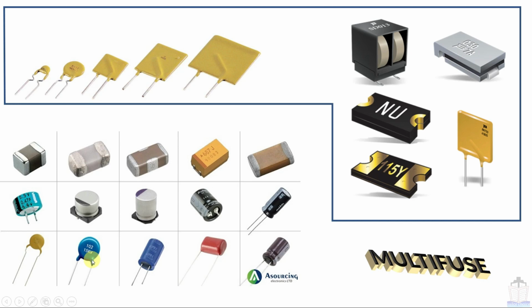So the question is, how will you come to know whether this is a multifuse or a capacitor? Some value of capacitance will be written over here. Here it is written 102 15 kV, etc. But on the multifuse you won't find any such data, meaning you will not find voltage and all that. You will find only the temperature and some other values that are not relevant to capacitance. So by seeing this you can identify. Another thing is that these multifuses are very thin, whereas these are a little bit thicker. So by these two ways you can identify which are the multifuses and which are the capacitors.